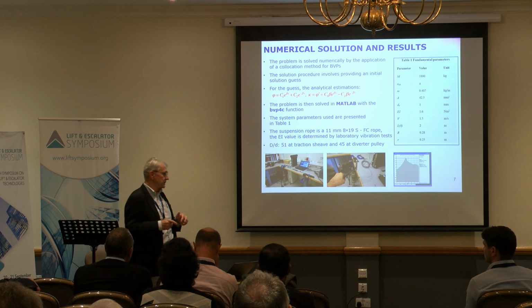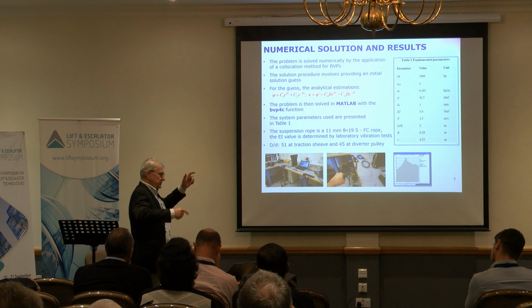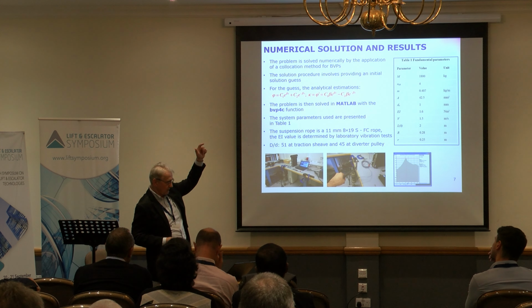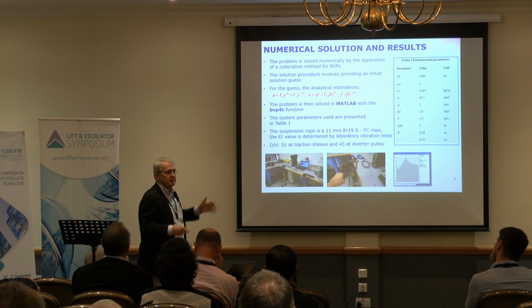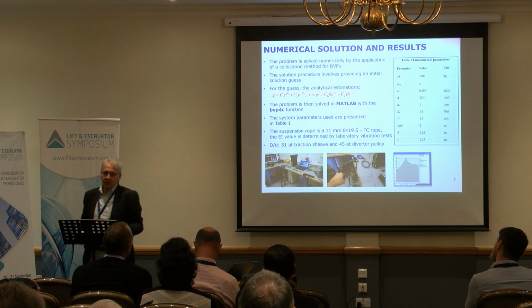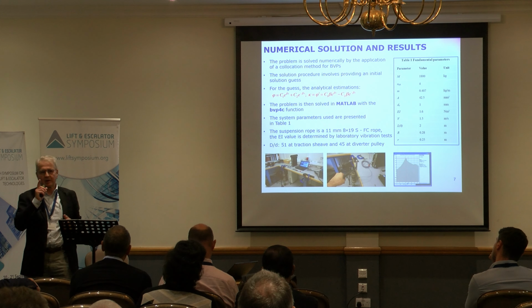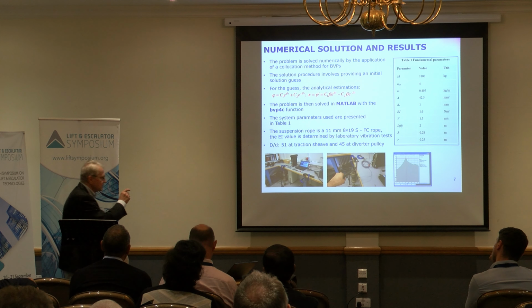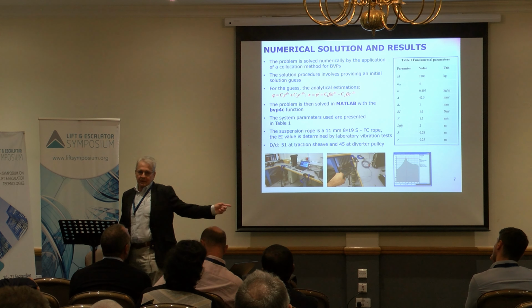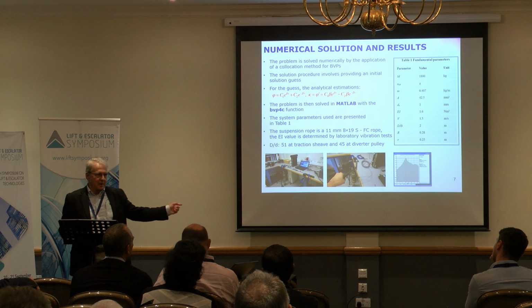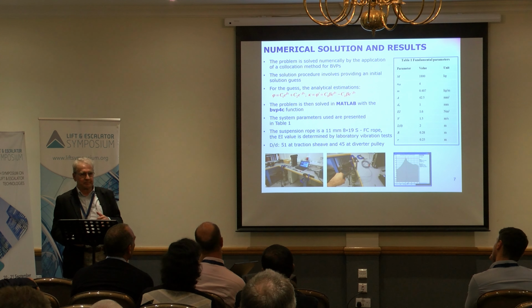A boundary value problem is a system which has boundary conditions at the upper end and the lower end, and the shape of the rope is described by the differential equation in terms of not time, but in terms of S. So we earlier had a simplified model where we assume that L is constant.